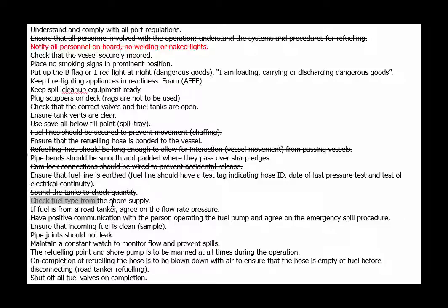Check the fuel type from the shore supply. Yeah, we need to make sure we get a bunker note from the supplier. Make sure we got the right fuel, low sulfur diesel. Alright, we want to agree on the flow rate and pressure, that's true. But the main thing we want to know is that we have positive communication with the person operating.